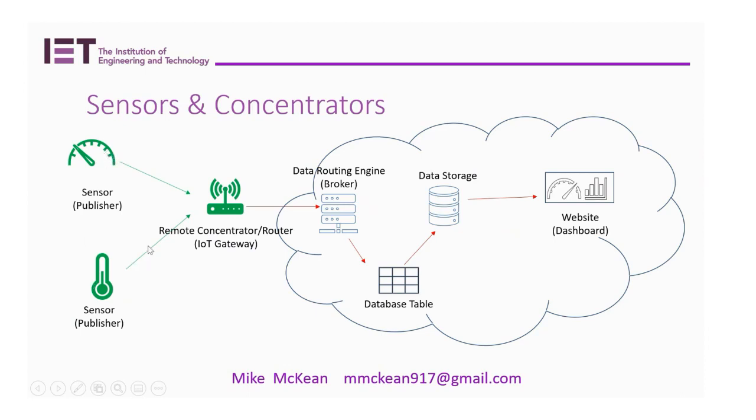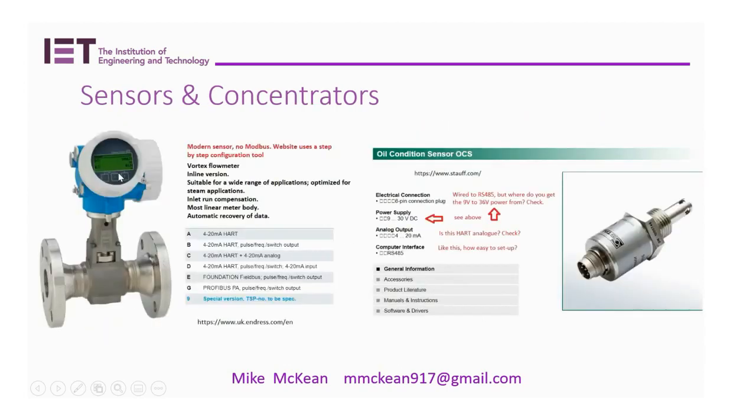Yeah, install them all up, but on your patch panel, connect one at a time, and then check for noise, etc. And hopefully you haven't got any noise. But if you have got noise, typically it's what's called a ground loop or an earth loop, because one of these devices is humming. Right, back to where we were.